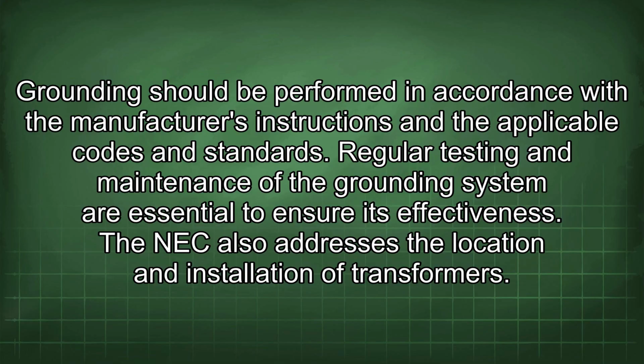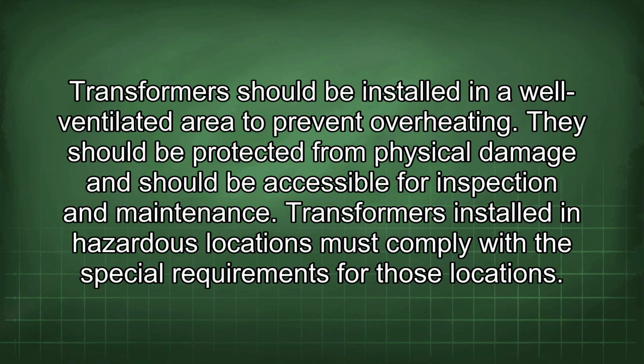The NEC also addresses the location and installation of transformers. Transformers should be installed in a well-ventilated area to prevent overheating. They should be protected from physical damage and should be accessible for inspection and maintenance. Transformers installed in hazardous locations must comply with the special requirements for those locations.